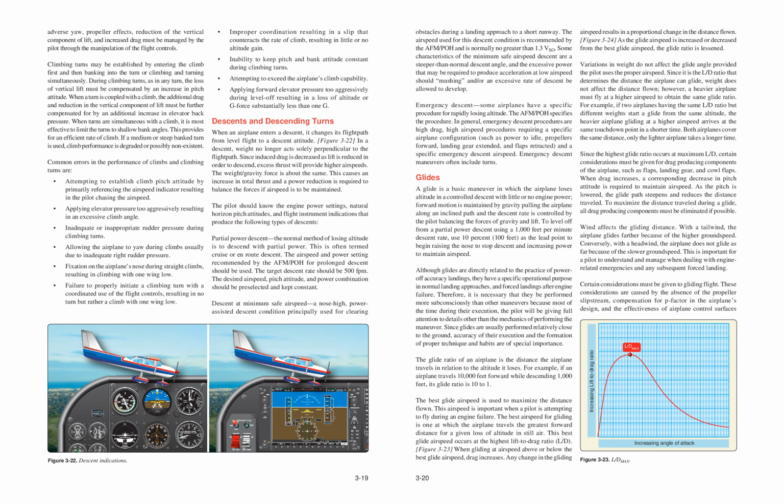pitch attitude. When a turn is coupled with a climb, the additional drag and reduction in the vertical component of lift must be further compensated for by an additional increase in elevator back pressure. When turns are simultaneous with a climb, it is most effective to limit the turns to shallow bank angles. This provides for an efficient rate of climb. If a medium or steep bank turn is used, climb performance is degraded or possibly non-existent.